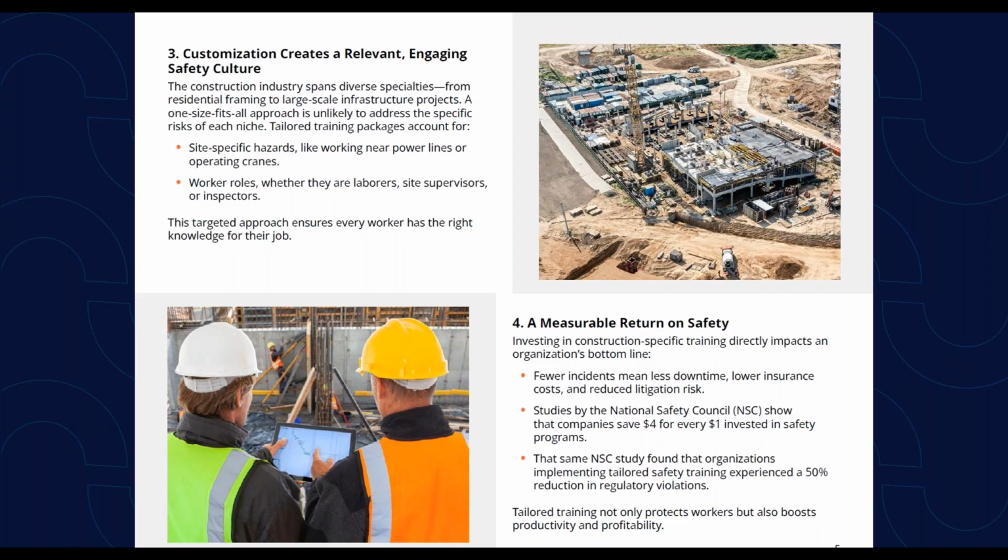So what we talk about here is understanding our site-specific hazards, everyone rallying around following the best practices. Before we all get on this scissor lift or all get on the scaffold, we're all going to be wearing our lanyards and our fall arrest systems and our harnesses. We're going to be holding ourselves accountable and calling ourselves out if we see someone not doing it the correct way. We're all responsible for each other, keeping that safety culture. And hey, did you take your training yet? I know it's due in a week. Did we all do that? We all just got to get it done, that type of stuff.